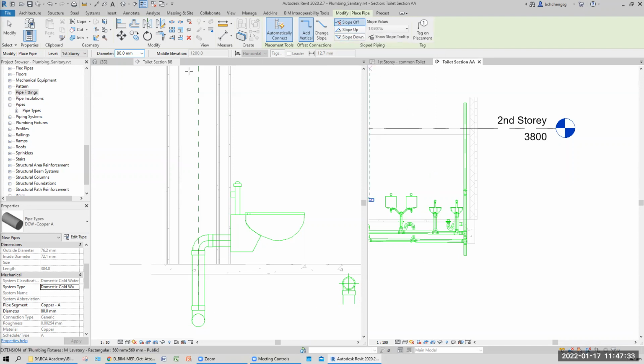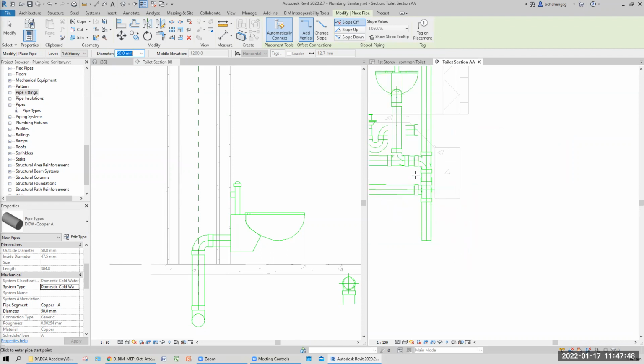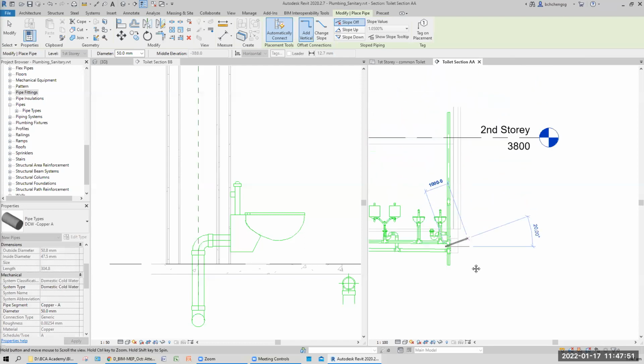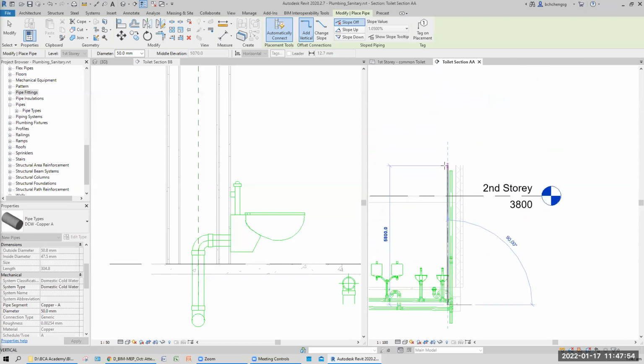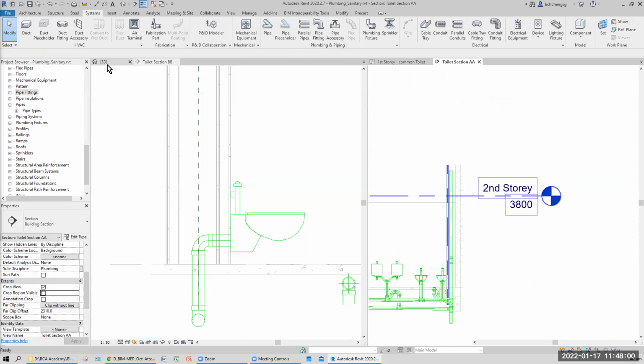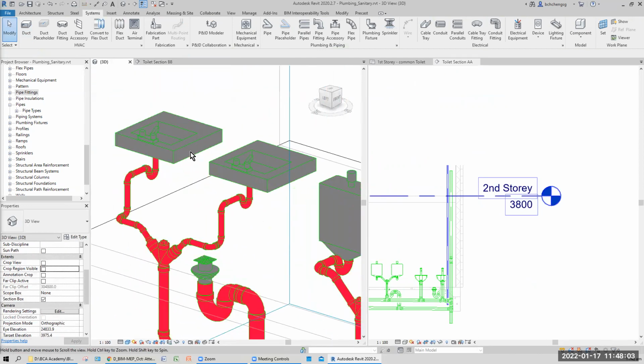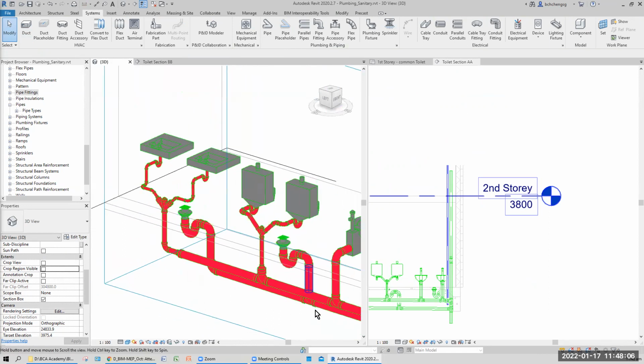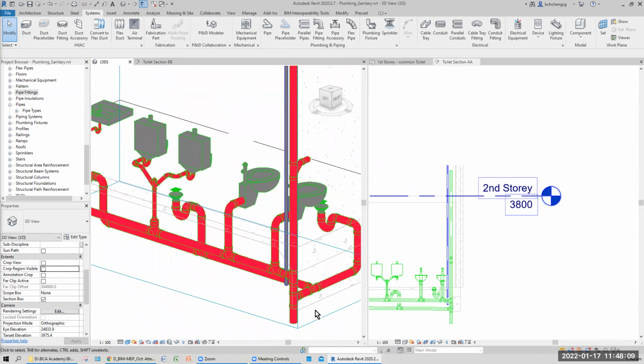Then there's no sloping. Now the default pipe size supply from the pump is 50 mm, 2 inch. Okay, 50 mm. So you just simply draw randomly anywhere here first. Don't worry. Somewhere from here, draw one pipe upward to the next level like this. Because you're going to supply to other floors, so you can see the color should be blue. You look at the 3D. If this doesn't show blue, then you should know how to apply the color, right? What's the color code? Just now. So apply a filter, adjust to this.